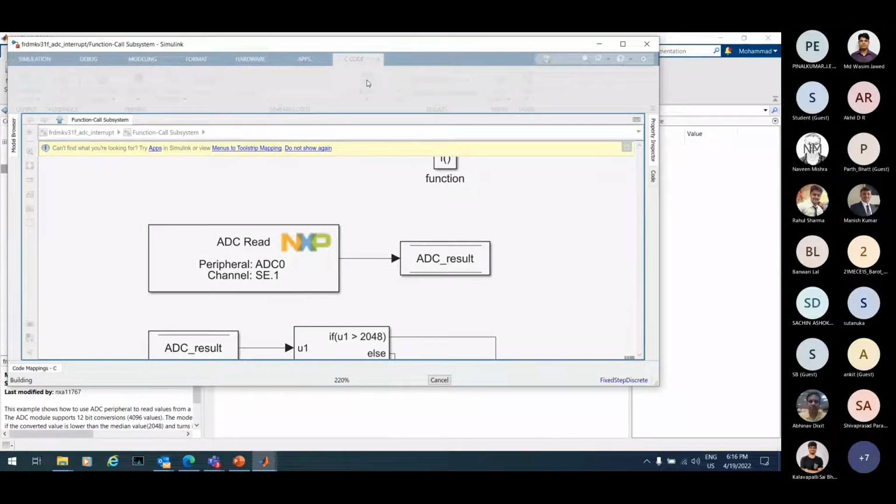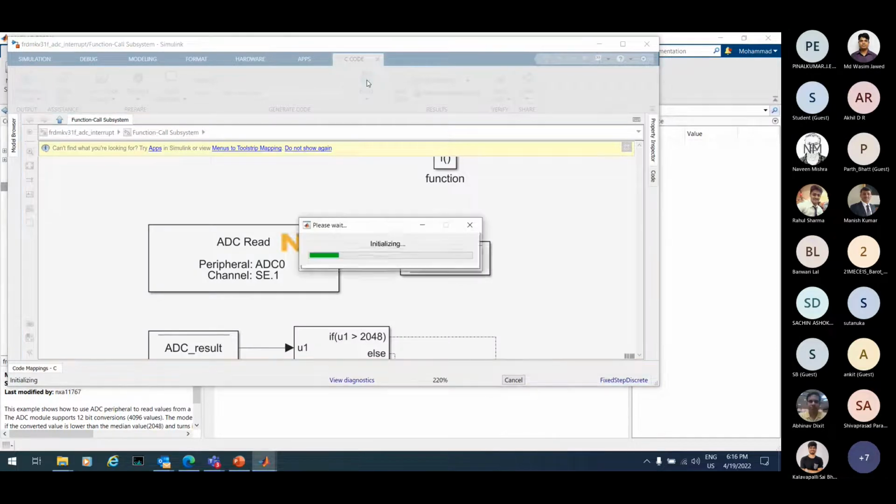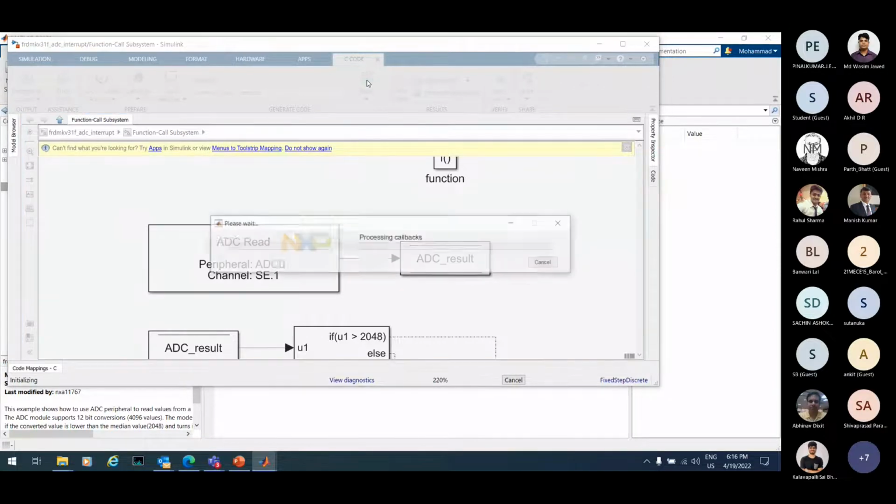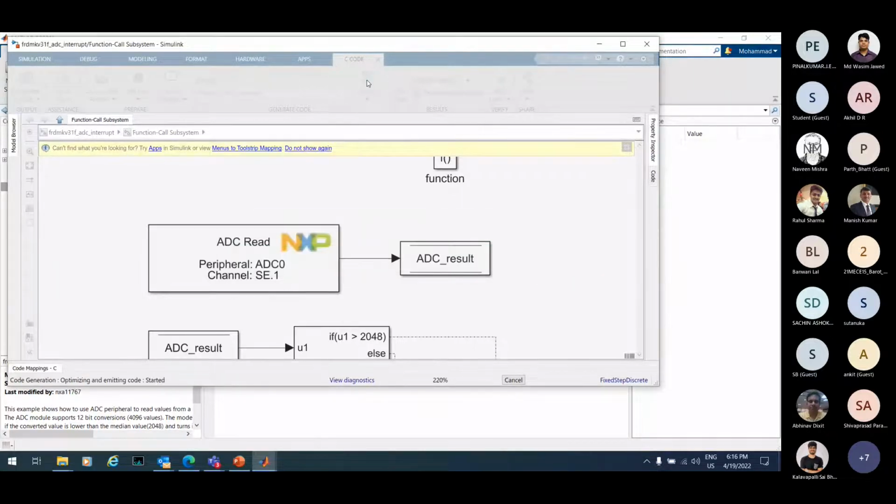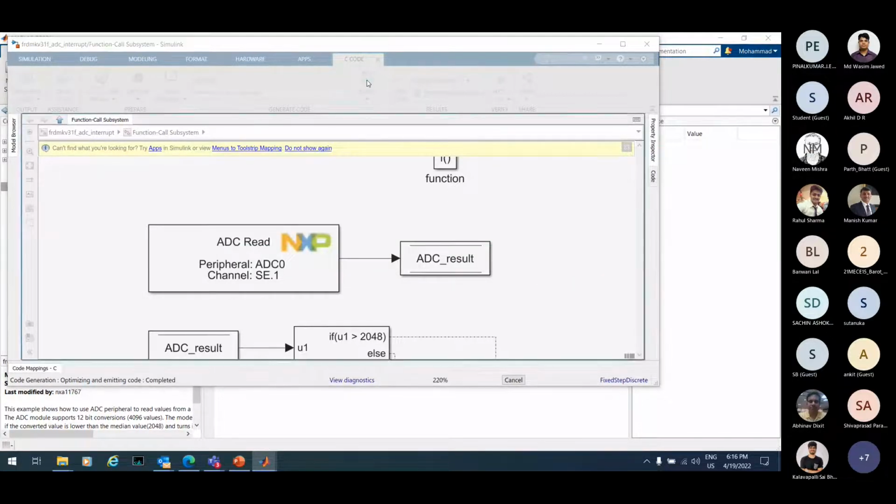MCU. So you first open MATLAB, make a system, simulate that system, see all the result is fine, then build the code and burn this code directly to your hardware. So it actually bypasses a lot of other things and makes your life easy, and makes sure that whatever you are doing, you are first simulating it, making sure that everything is correct before burning to the hardware, to make sure that hardware should not misbehave, or should not go bad when you start running it,